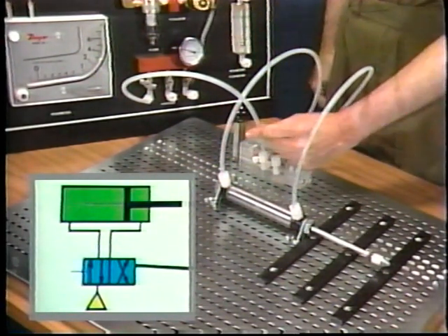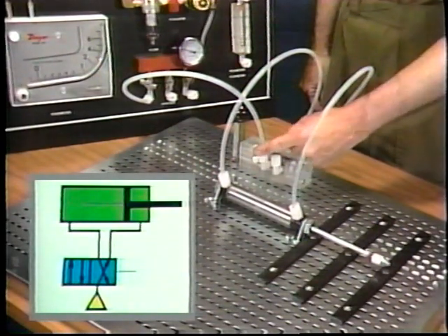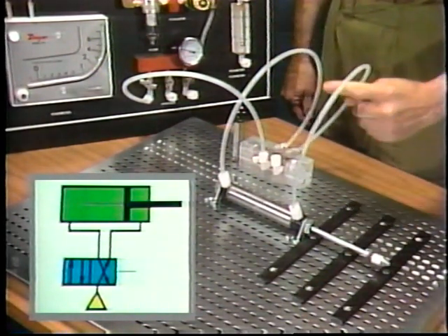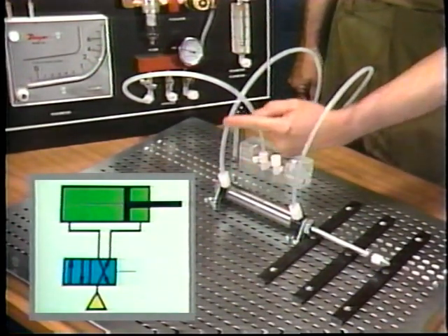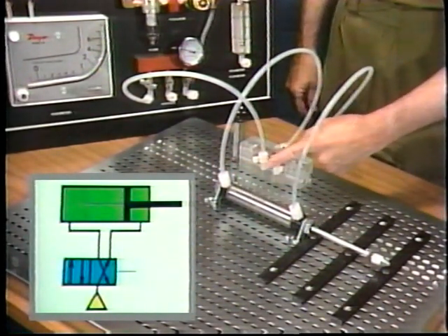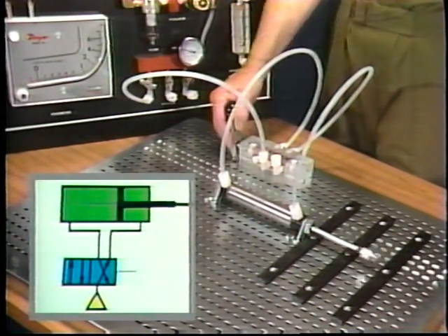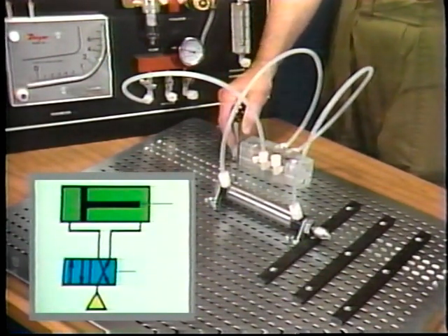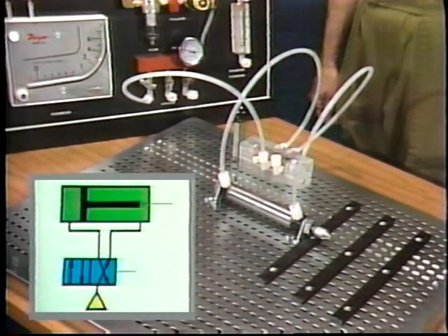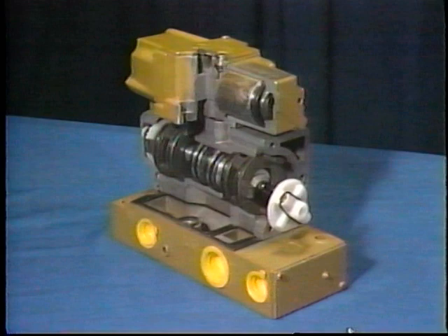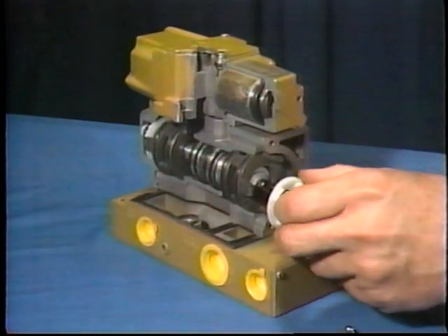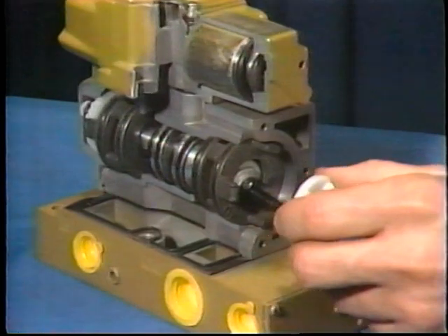When we move the valve into the other position, the supply pressure is connected to the rod end of the cylinder. And we've created a passage for air to exhaust from the cap end through the valve to the exhaust port. So you can see by using the four-way valve, we can easily and quickly control the direction of a pneumatic cylinder. Four-way valves are also available with 5 ports and provide the same basic control of flow paths as the 4-ported models.